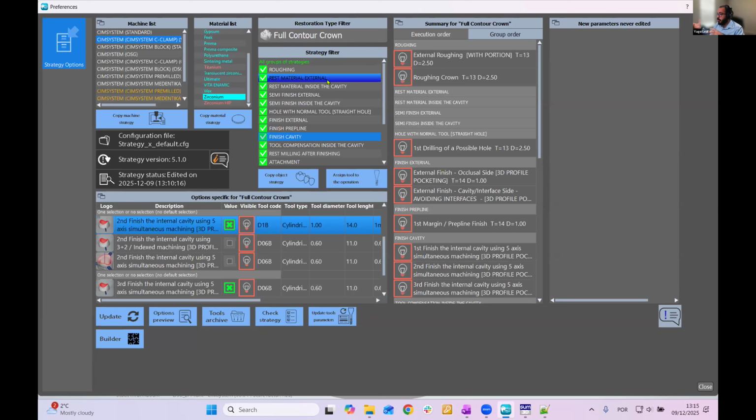Using the previous tool diameter might give you a little bit of air milling because we're just considering, well, the previous tool was 2.5, now I'm using the 1 millimeter, so I'm passing through those areas. Usually we tend to be a little bit safer and do a little bit of air milling when using that, to compensate for possible scenarios where we don't go exactly on those areas. So we prefer to air mill a little bit instead of not checking exactly where that tool passed and plunging into the material and causing a tool change or tool break. So we have those two ways.